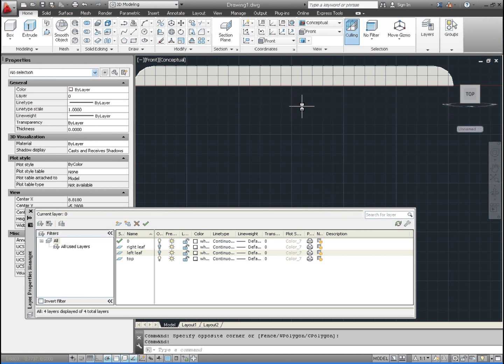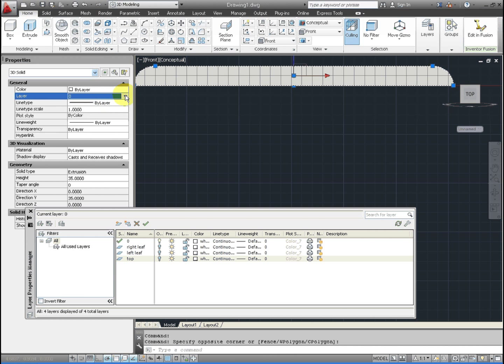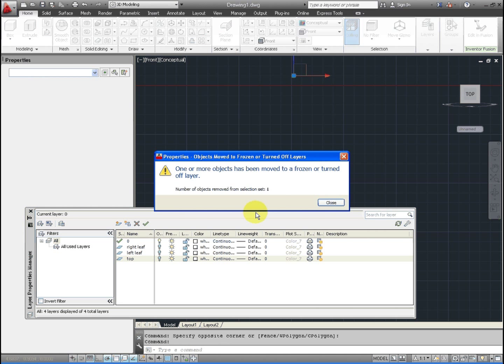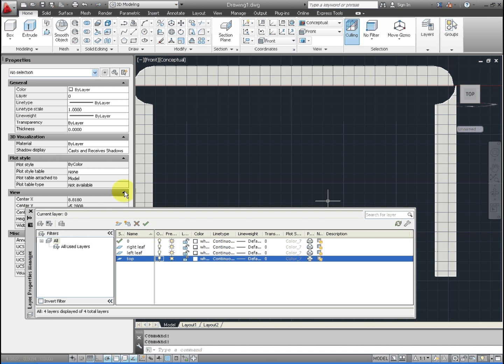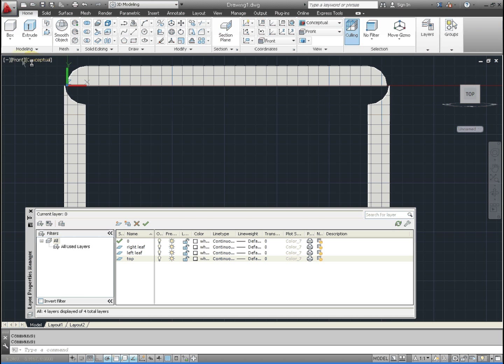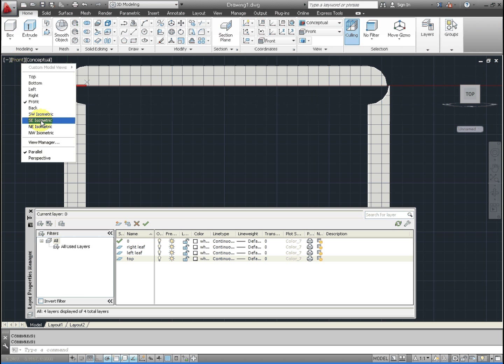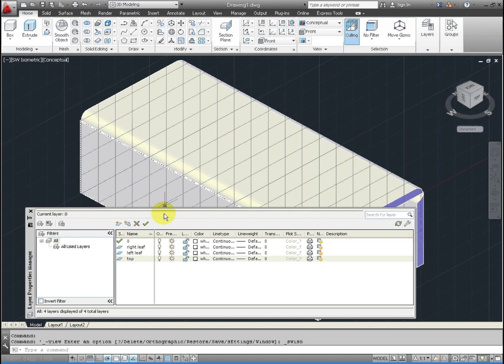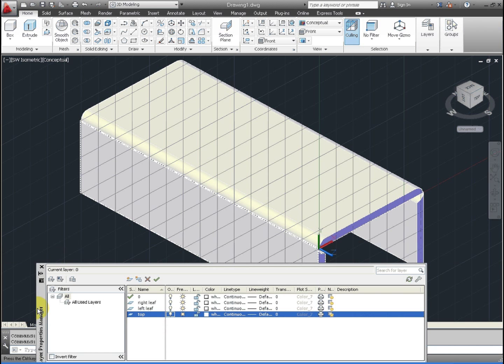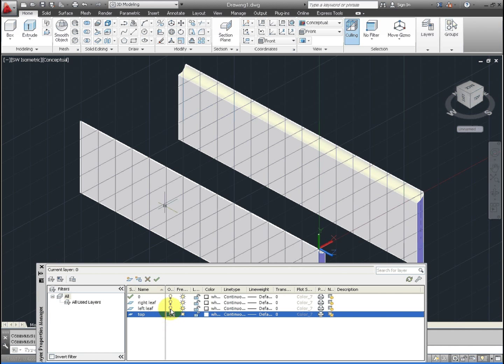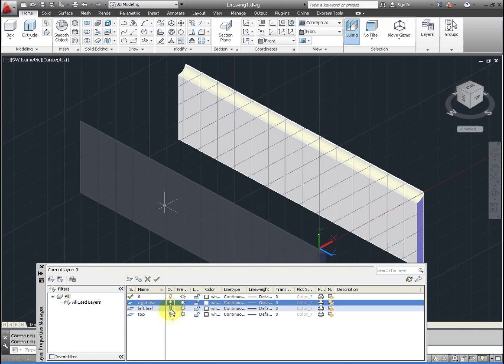And again, it's telling us that the layer is off, and then we'll finish that up with the top, or the work surface. Select the item, right click on it, hit the properties, and put it on the top. So right now everything's invisible, so let's go ahead and turn these all back on. And then before you end this lesson, go ahead and inspect everything. So in this lesson we have created the work surface, the surface of the table, and the leaves. And we've extruded the objects. So make sure they're on the layers, and you've completed the first lesson.